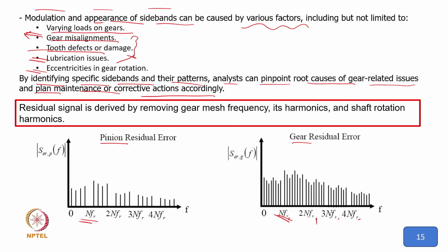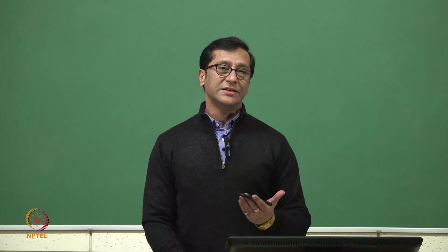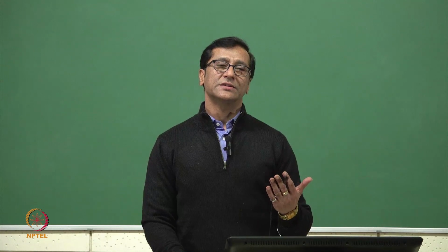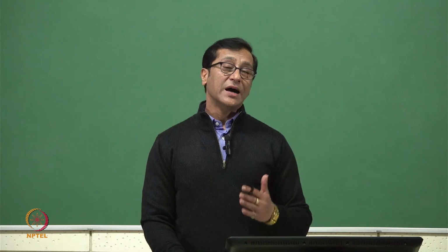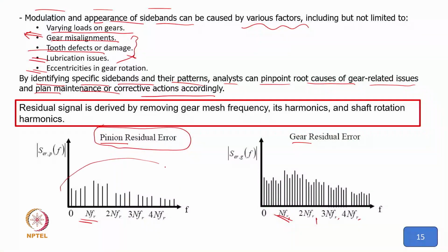No, not necessary. So what they do, they go ahead with the residual errors. What is the meaning of residual errors? Whatever the difference is coming: I have a healthy gear, I get a response, and I know that the gear has run maybe 1000 hours and it gives us some frequency response. We subtract that response and come up with only the residual errors. Now, if there are residual errors or there are sidebands, I can analyze this and I can get better results from this. So, this is important to understand.